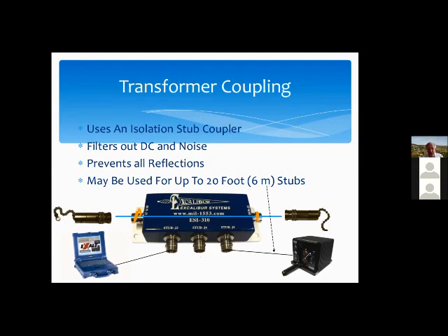This has to be connected to a stub. The bus controller connects to a stub. An RT connects to a stub. Monitors connect to a stub. So what connects to a bus? The only thing that connects to a bus is the bus, which is to say a wire. Why would I want a wire here? Because this has a 3-stub coupler, and I'm going to put it in the part of my lab where I've got 3 of my RTs. And then I might have my bus controller and another RT on the other side of the lab.